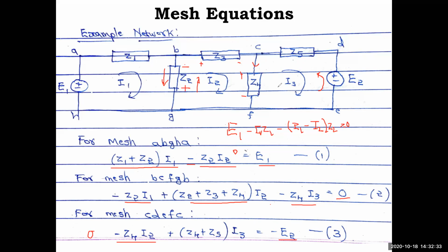You'll get I1, I2, I3, all the three currents. Okay, so what is I1 you will get? So that is Z2 into I1 minus, because it is not self, no, mutual. So mutual always comes minus Z2 into I1, and the self Z2, Z3, Z4, three resistances are there, all three will be added into I2. So this is the self. Again you have mutual here Z4, so that's why minus sign, Z4 into I3. So this is the way.